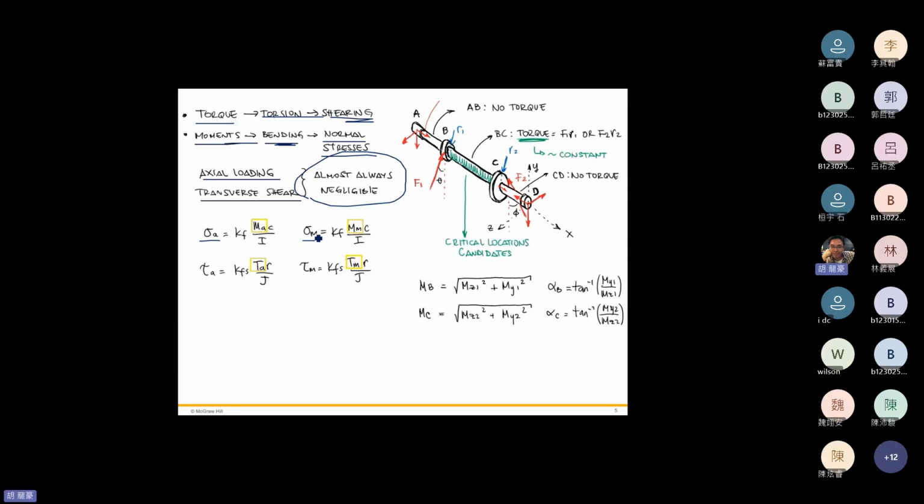In this case, we have torque applied to the shaft, so we have to take into account the shear stresses, the alternating shear stresses and the mean shear stresses. Kf is the fatigue stress concentration factor, and Kfs is the fatigue shear stress concentration factor.